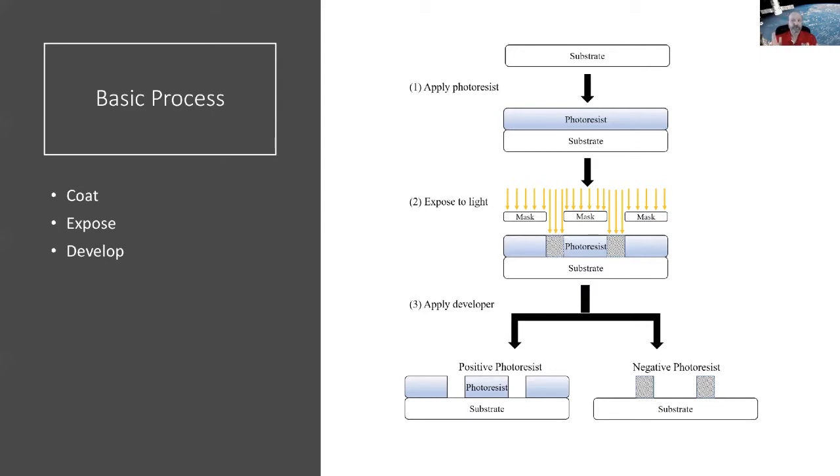You design this in layers, and then you transfer the layers onto the wafer surface and pattern the different materials that you use in building this product. So it's a layer by layer process. At each layer you have to do what's called photolithography. Okay, and that's what this slide shows you.